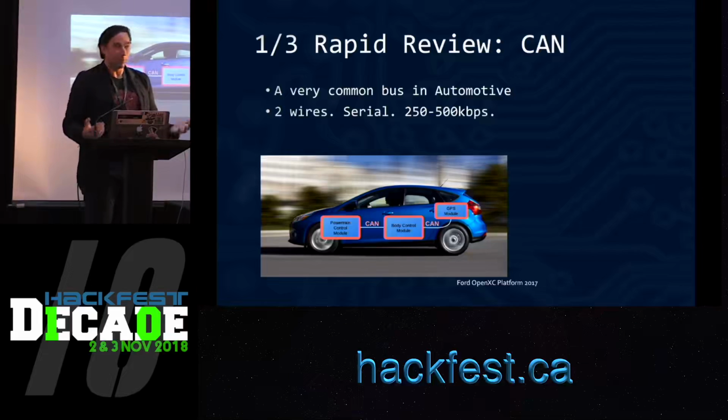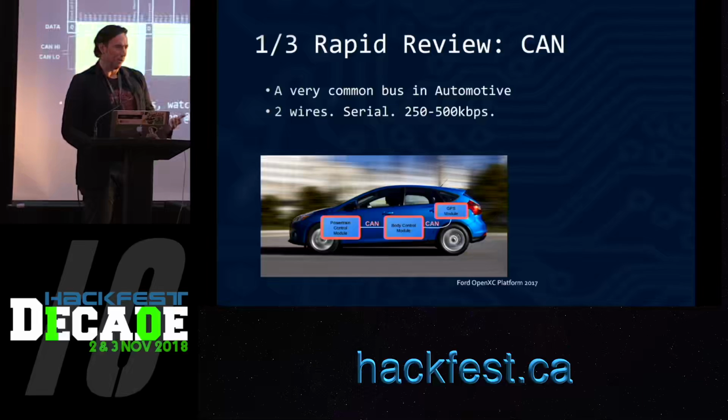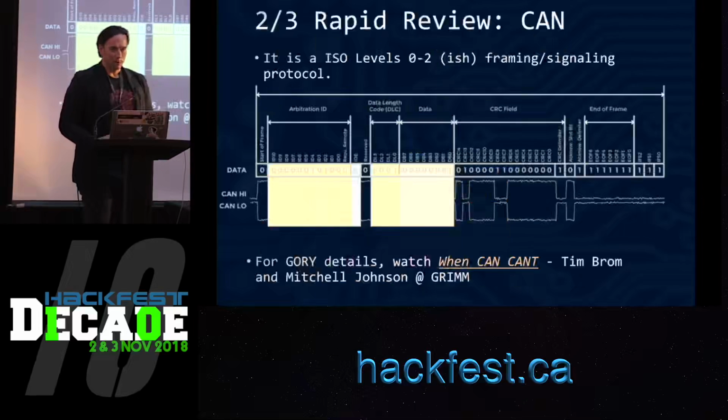But this is, of course, from the 80s, and it runs super slow. And the size of the frames is super small, but everything still kind of works. They pack it like this. They add another really interesting arbitration mechanism. If you think about Ethernet, it's got that collision detection and backoff. What they do here is the arbitration IDs are prioritized.